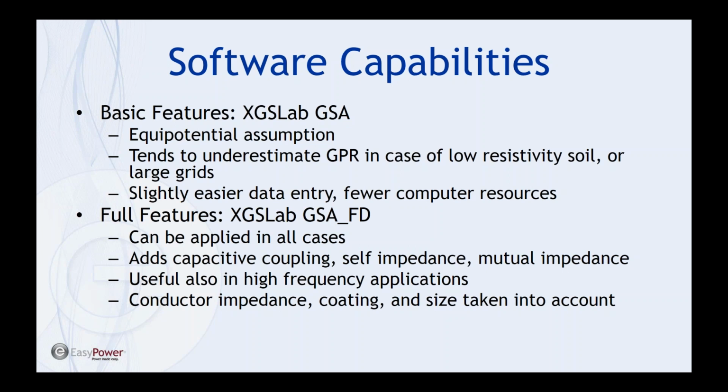The GSA module, or this level of module, is also useful. It's definitely a step up over the IEEE 80 spreadsheet because you get the numerical and graphical output useful for investigation of GPR, leakage current, surface potential, and touch and step voltage distribution.